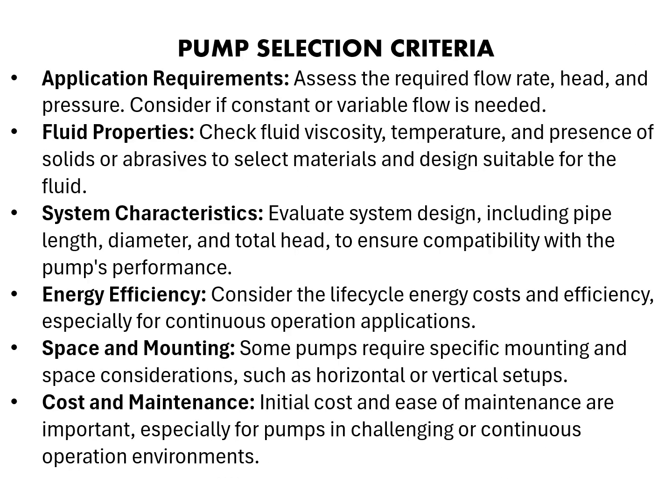Now let us see how the selection criteria work. First, application requirements: in which application are we going to use the pump? It may require a constant flow rate or a high head pressure. Another one is fluid properties. What kind of fluid are we going to use? It could be high or low viscosity, high or low temperature liquids, or contain solids. If it is a muddy area, some solids will also be there.